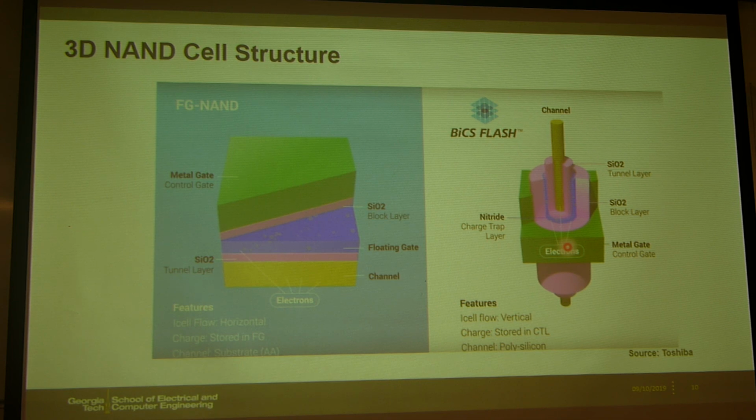So is the 3D structure monolithic or die-stacked? Monolithic or die-stack for the 3D? What I'm talking about in 3D is just in one wafer. Oh, so just one wafer. Yeah, and die-stack is not used here. Okay. But then you said there are like 200 or 64 layers of memory stacked already. How do you do that within one wafer? I will explain in later pages.